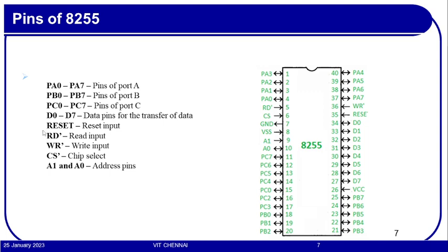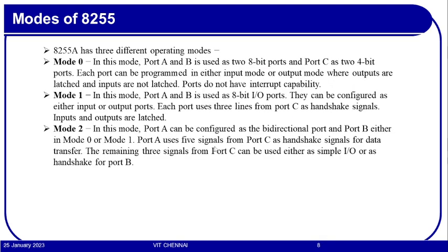All these things are inputs from the microprocessor. So reset will reset all the internal registers of the 8255. This is a global reset which will be received by the 8255 from the microprocessor. Now, the modes of the 8255.